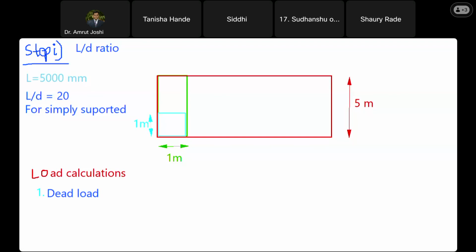Do you remember, Siddhi, last time we gave the deflection check for beams, where we said that the L by D ratio should be 20 for simply supported, 26 for continuous, and 7 for cantilever. Do you remember that? Shreya, do you remember that? Yes, sir. Okay, so let us go ahead. So 5000 upon D should be equal to 20. That gives me, what should be the value of D? Tell me.